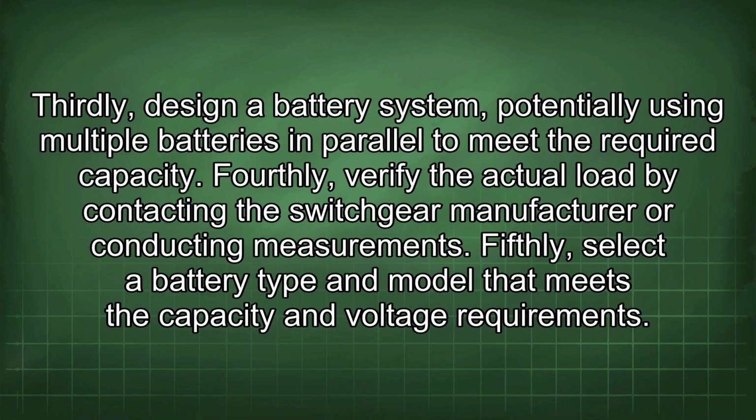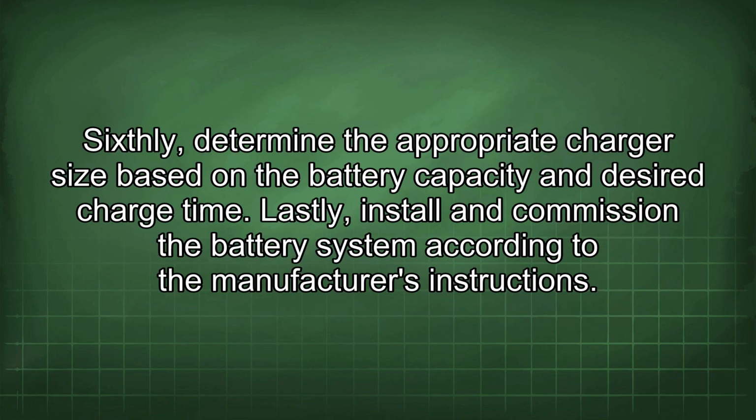Fifthly, select a battery type and model that meets the capacity and voltage requirement. Sixthly, determine the appropriate charger size based on the battery capacity and desired charge time. Lastly, install and commission the battery system according to the manufacturer's instructions.